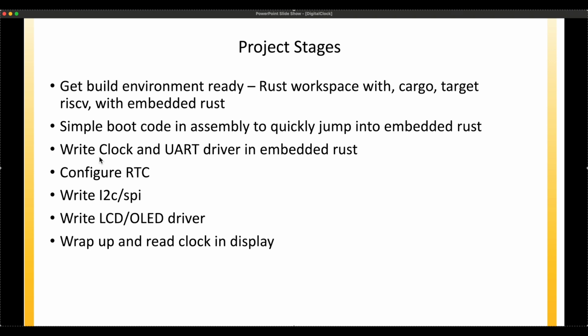This clock driver is to set the system and core clock, and then we configure the RTC, and the RTC driver we would also write in Rust, followed by the I2C or SPI driver, based on whatever interface is supported by the LCD or OLED display that I'm going to use. Then we wrap up this project with the demo, to show that the clock is being displayed on the LCD or OLED display.